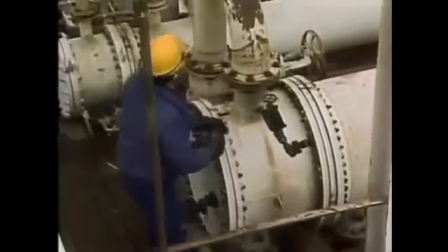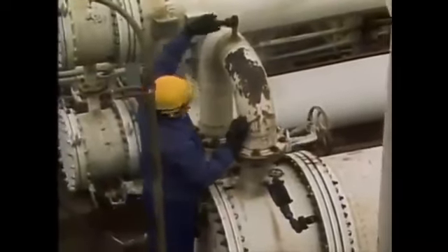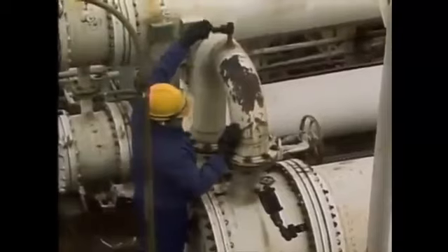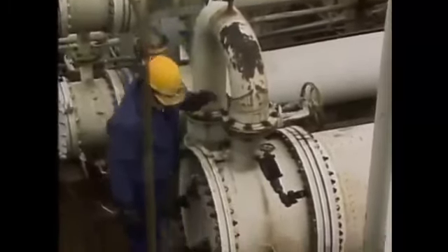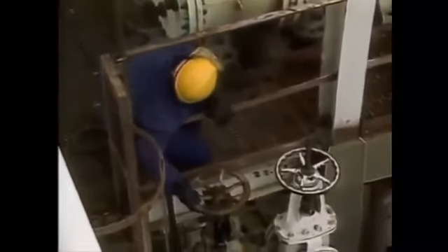Regardless of how gases get into the heat exchanger, the unit must be vented to allow them to escape. Repeated venting may be necessary to ensure that the heat exchanger remains free of air and other undesirable gases. However, excessive venting can cause its own problems. For example, each venting may allow a small amount of the process fluid to be lost from the process. This reduces the efficiency of the process.